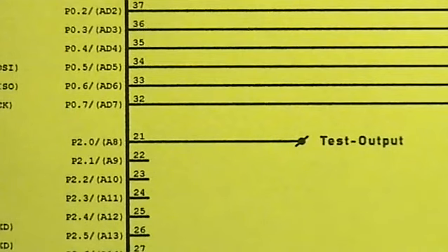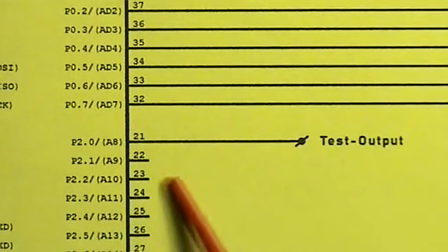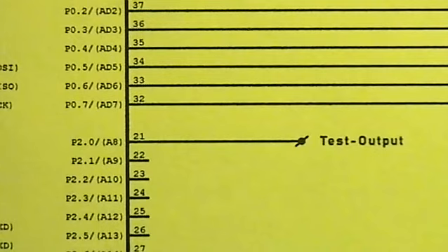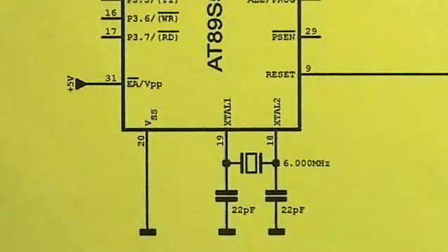I intended port P2.0 as a test output. The oscillator circuit integrated in the microcontroller is completed with a 6 MHz crystal and two 22 picofarad capacitors.